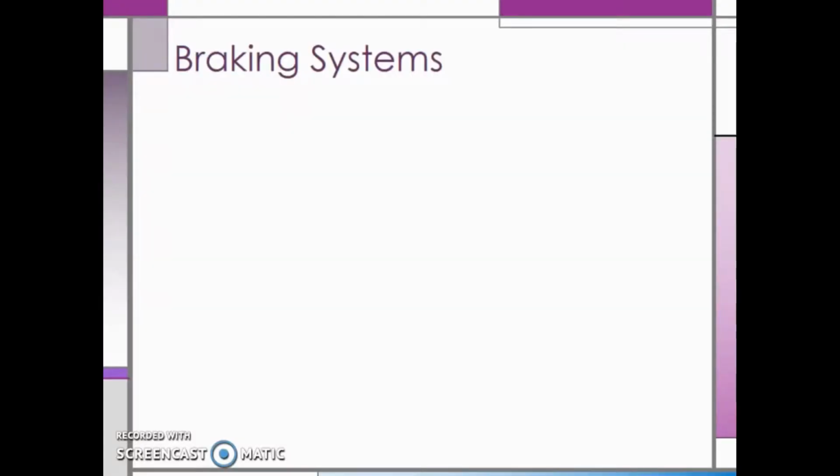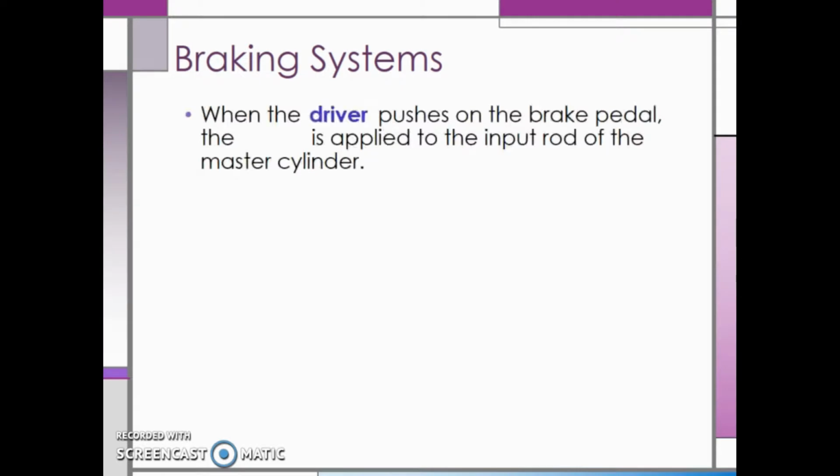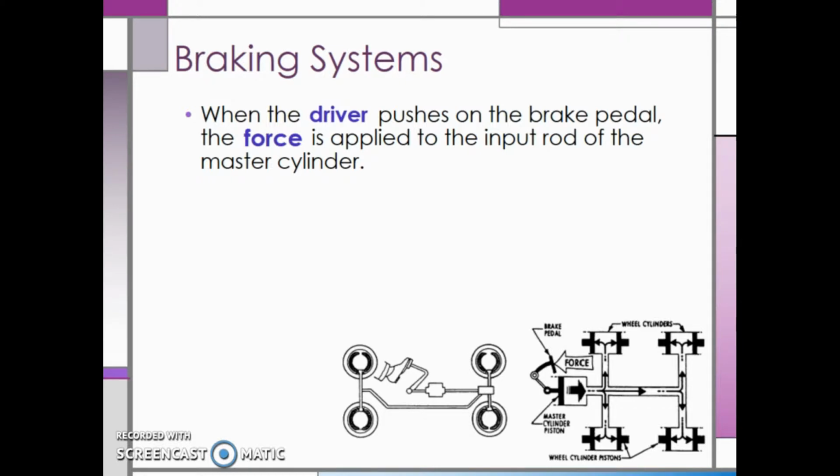In the previous video, we looked at some examples of finding the pressure, force, and area. Now we are going to look specifically at how the brake system in a vehicle works. When the driver pushes on the brake pedal, the force is applied to the input rod of the master cylinder.